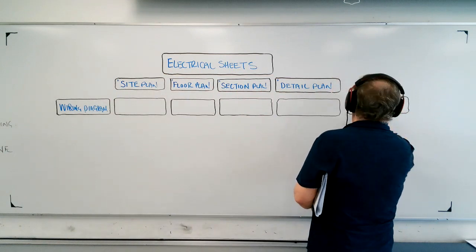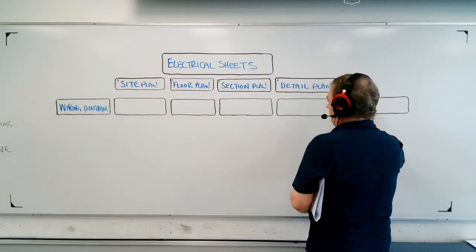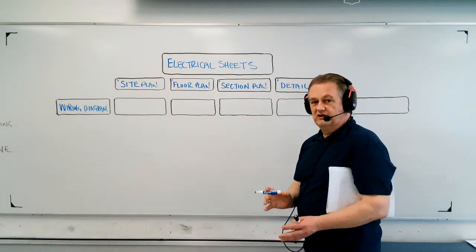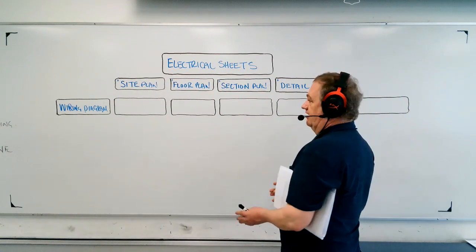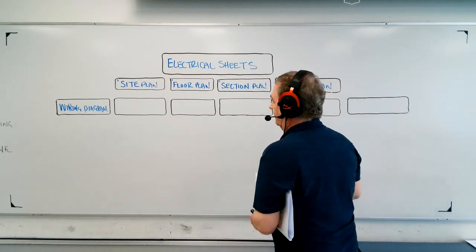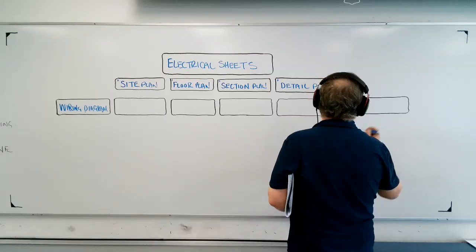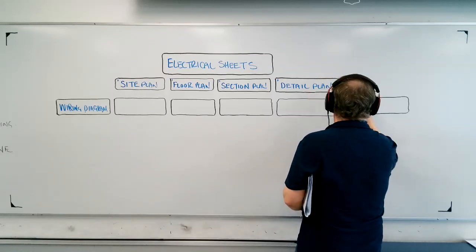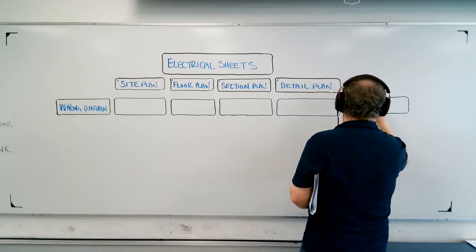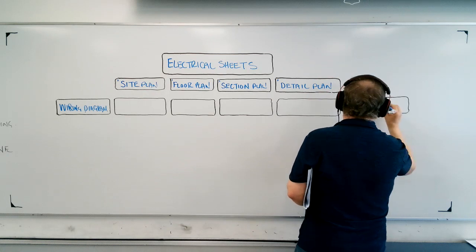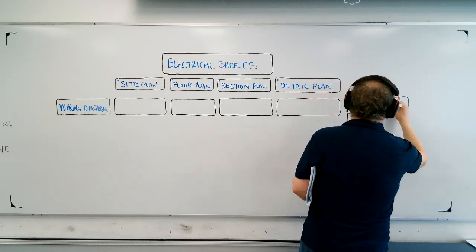Another thing that you can see, and a little bit different, of course, is that the wiring diagram usually shows the location of equipment and the routing of conduits and things to bring wiring to them. A schematic is actually usually more just electrical flow, okay? Schematic.